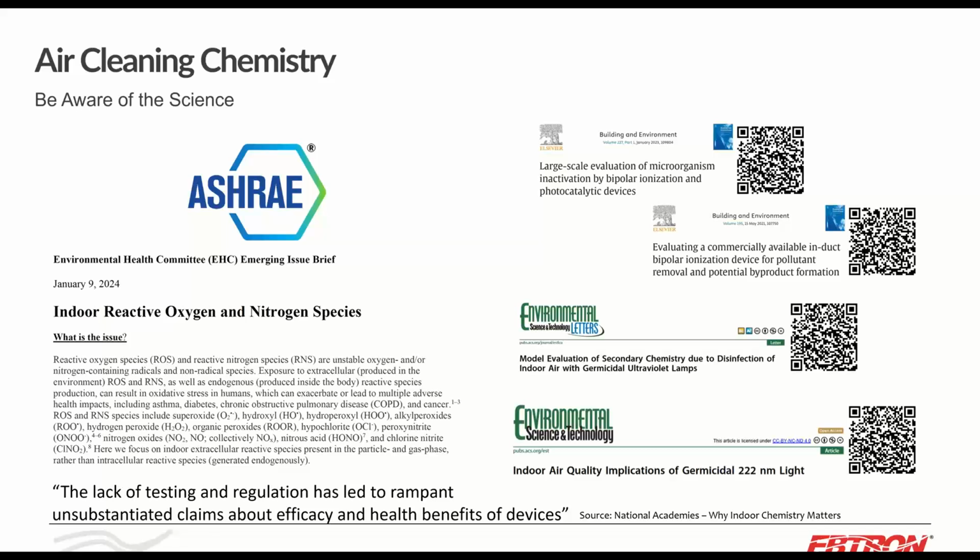So NIST actually did a study where they put some UV in the bathroom, and they found that the urinal cakes were off-gassing some VOCs, and the UV reacted with it and caused more complex VOCs and particles to evolve, generating some particles. So we have to be aware, as I like to say, measure twice and cut once. Ensure you understand what it is that you're putting in the building, what you're using, if it's beyond standard ventilation and regular filtration.